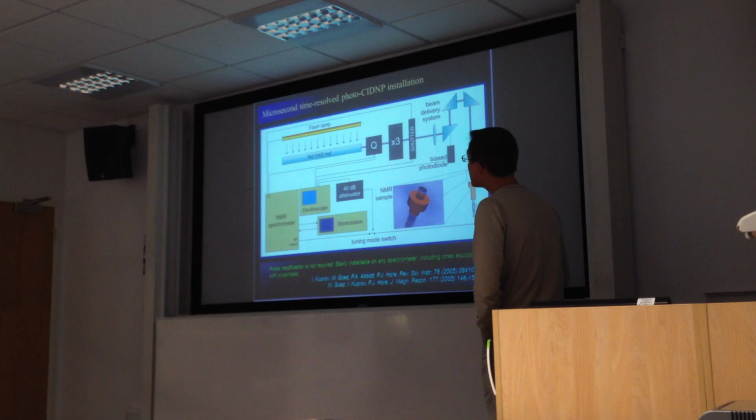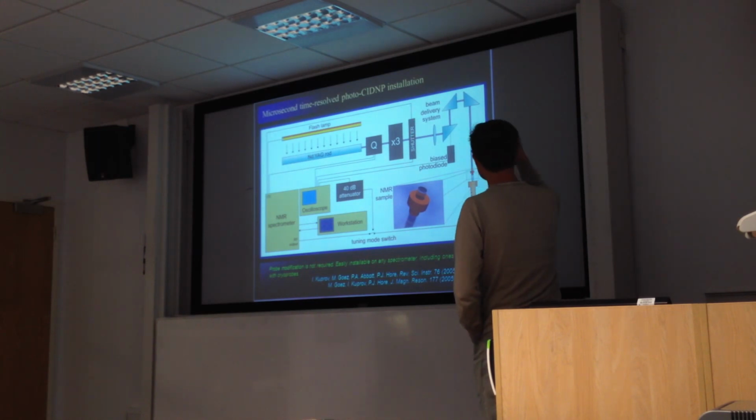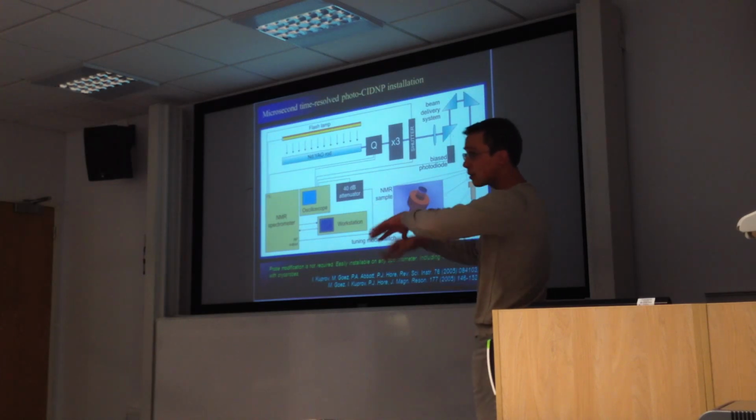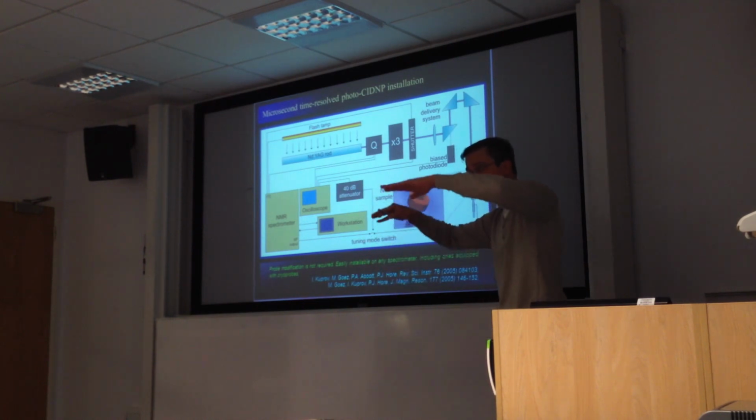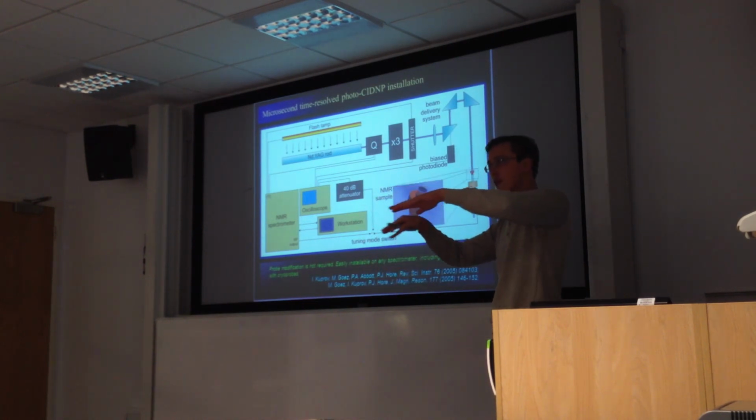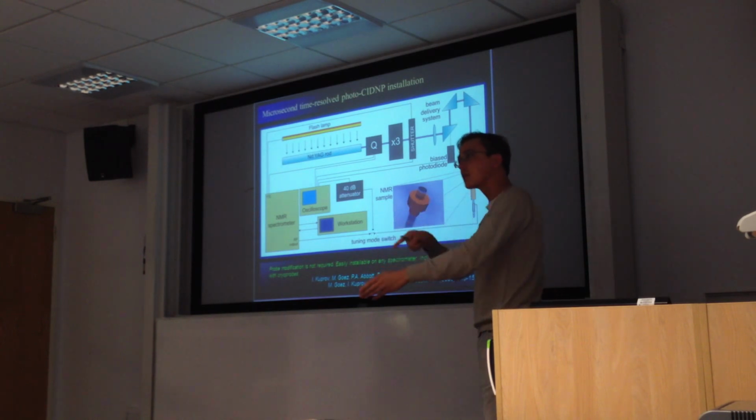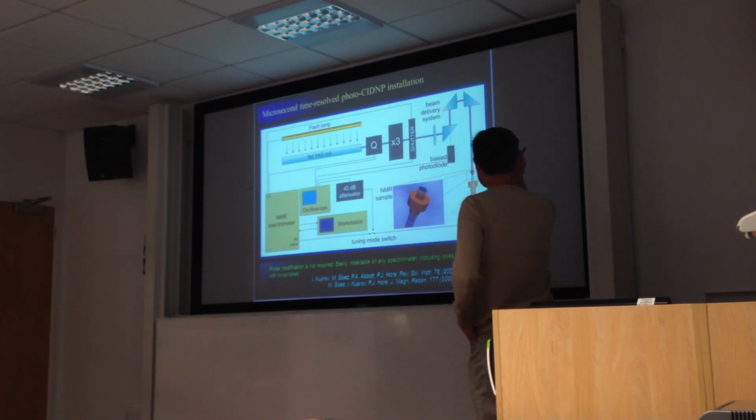We actually need 3 TTL lines from the back of the Varian. One controls the flash lamp on the neodymium YAG rod, the other the Q switch, which is what triggers the laser. And then there's a safety interlock shutter, which even I had to put in, because otherwise I would have been blind now. There's a photodiode at the target, which will actually tune the magnet geometry. Remember, the magnet is suspended in air, and that geometry is reproducible for a couple of hours, so you can still hit it, but you've got to retune it every time you do the experiment.